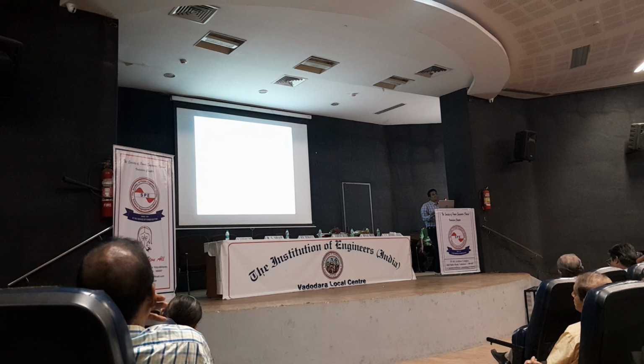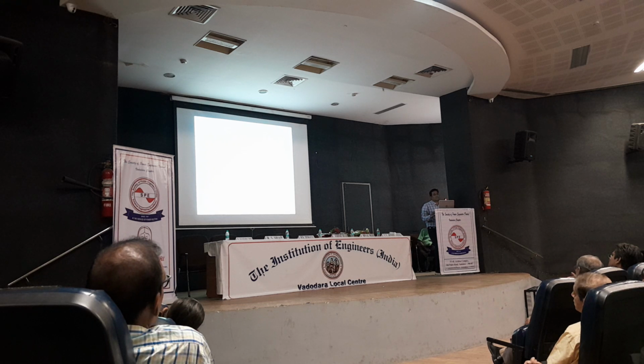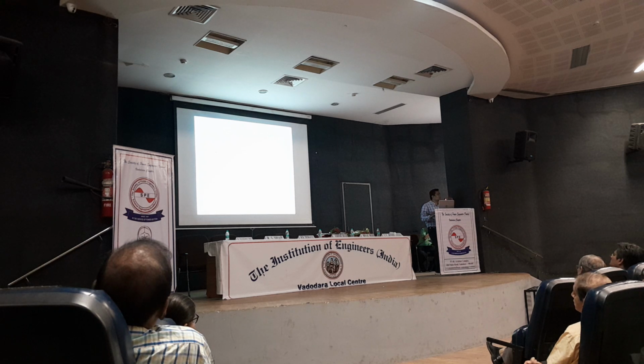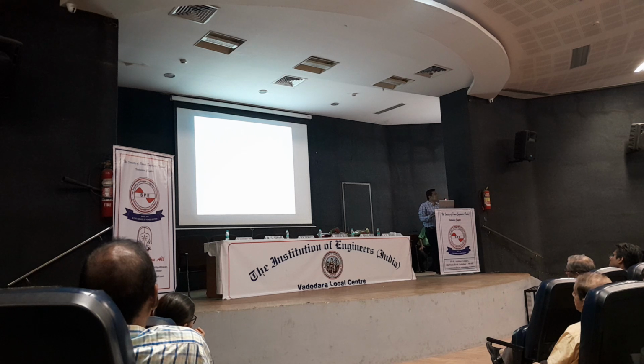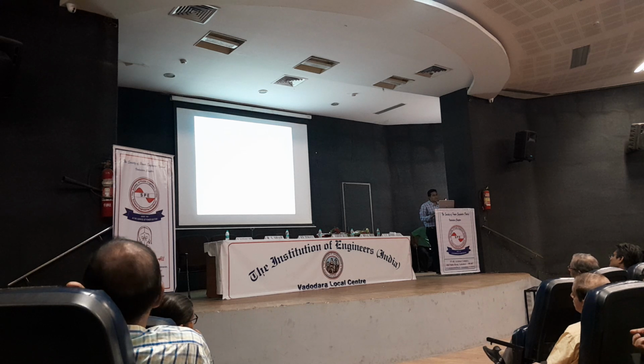Whenever you do the contingency analysis, direct violations will be indicated in reports. So you can observe what kind of violations there will be and which element is showing violations, whether there is an under voltage condition or an over voltage condition. That violation monitoring will be there. So you will be prepared in future if there is any kind of fault or disturbance in the system. You can easily take care of those disturbances if you did the contingency analysis. So contingency analysis is also one of the add-ons in this PowerWorld simulator.